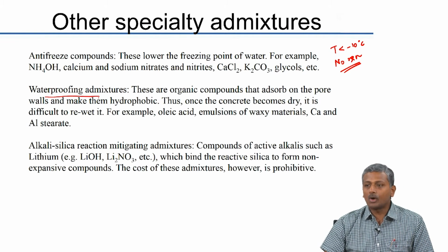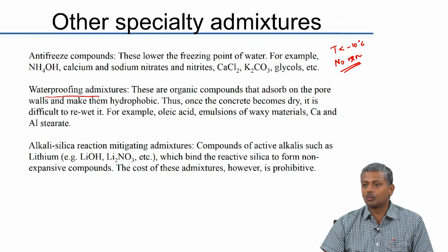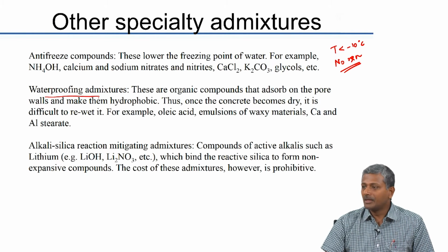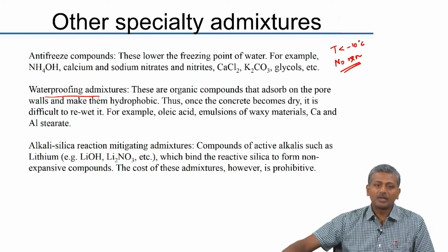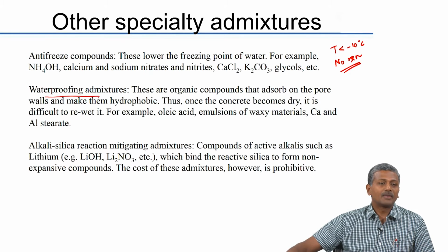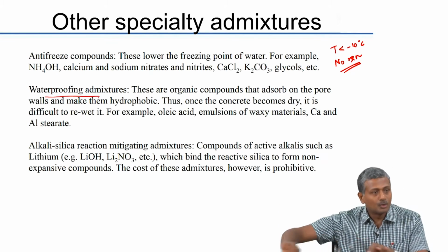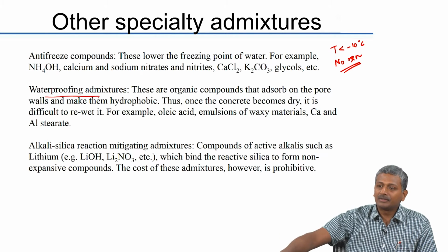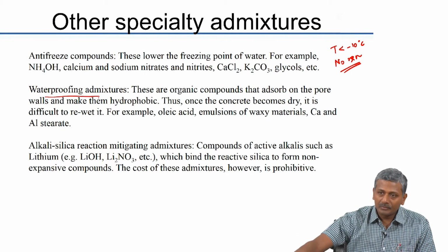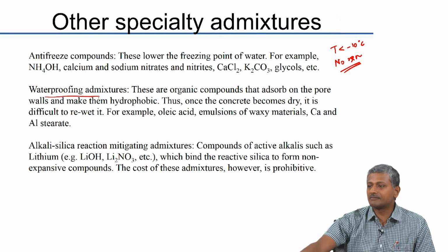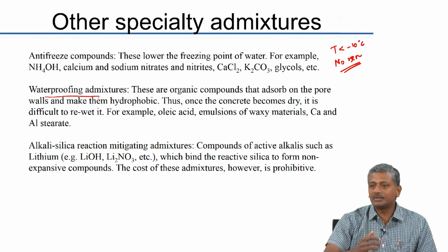These are essentially organic compounds that are adsorbing on the pore walls and making them hydrophobic. For example, like wax, right. If I do a wax treatment on the table, what will it end up doing? If I pour water on it, water will not stick to the table anymore, it will roll off, because the wax essentially makes the water non-wetting, okay. It makes the surface non-wetting. So, that is what these chemicals are doing.